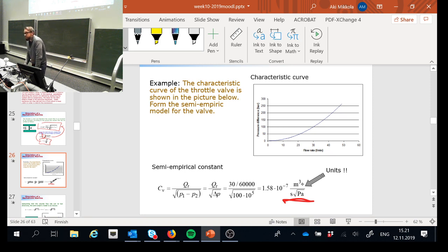And of course, you can convert this to any units you want, but when you're modeling hydraulics, it is highly recommended to use meters all the time, because once you start to convert these units, there is a high risk that you can introduce a mistake. And once there is a mistake, then of course it's not going to operate the way you think it's supposed to operate.